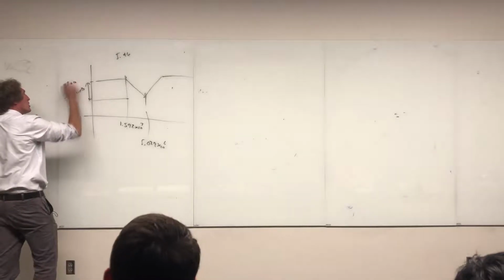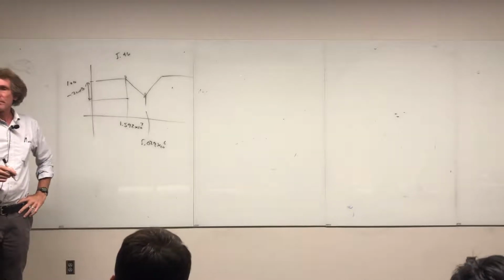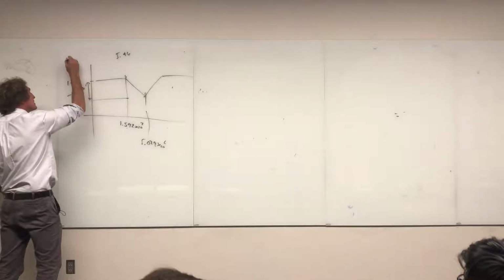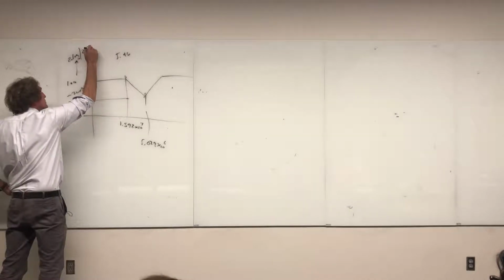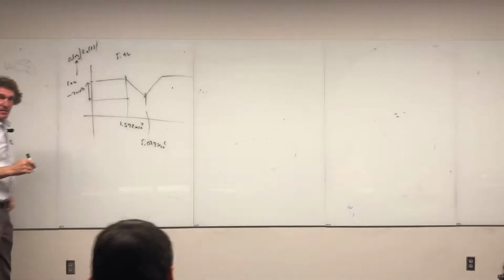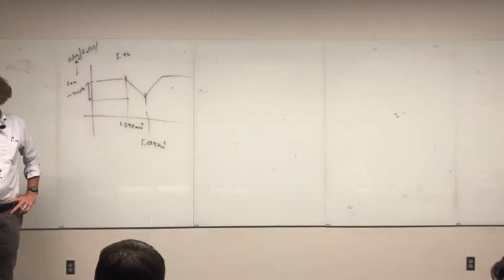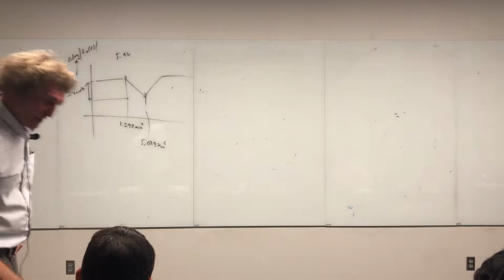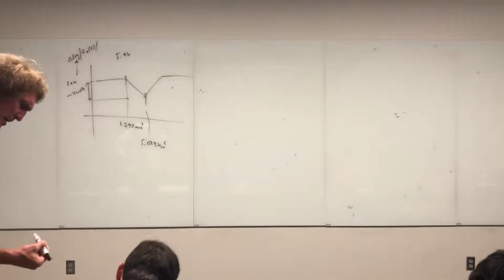Do you need the phase magnitude? No, that's it. This is a standard thing. What he's plotting really is 20 times the log of the magnitude of the impedance of a resistor versus frequency. It's not versus omega, it's versus F, in hertz. See it right there?